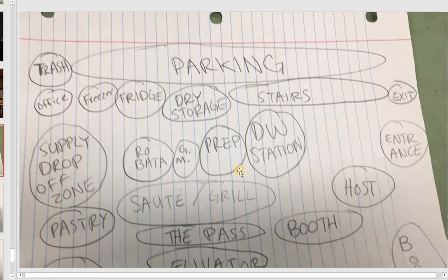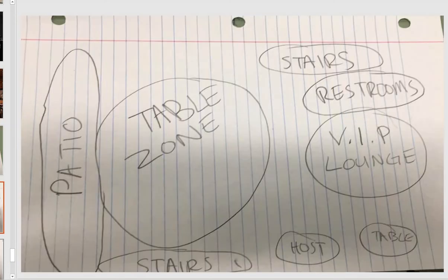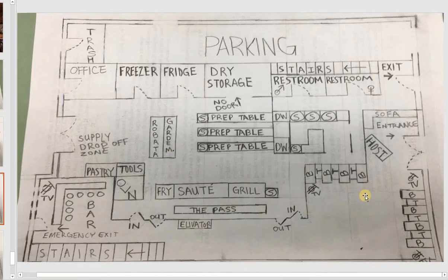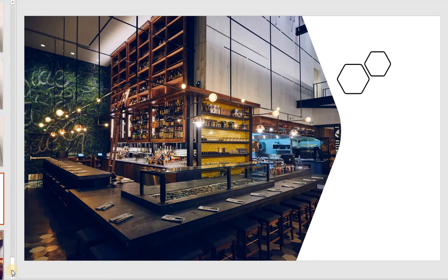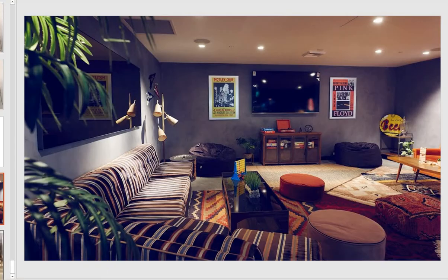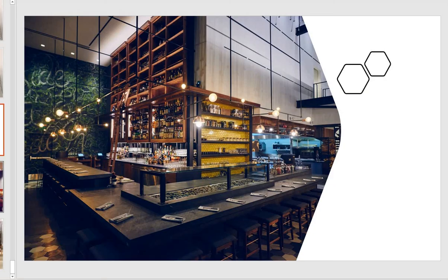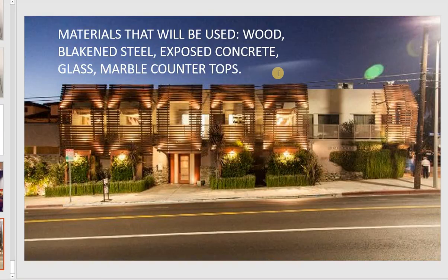This is the bubble diagram. That means the diagram for you to make sure which one you need to design for your project. After that, you develop a floor plan with the walls, the windows, and every room set up inside the building. You need to do it like that on the floor plan. And finally, you do the elevation, interior elevation or exterior elevation, depending on you. You can select which one you like, or both, or one of them, and share with everyone.